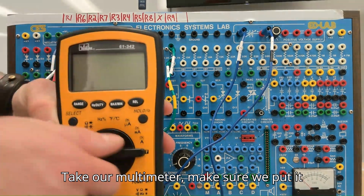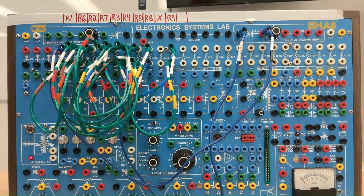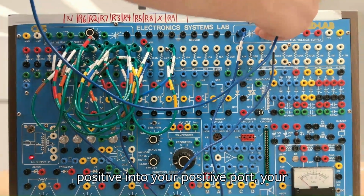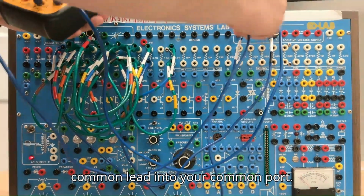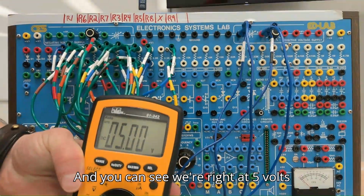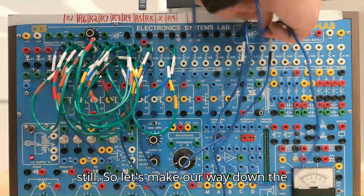Take our multimeter, make sure we put it in the DC settings. Take your voltage lead, positive, into your positive port, your common lead into your common port, and you can see we're right at 5 volts still. So let's make our way down the table.